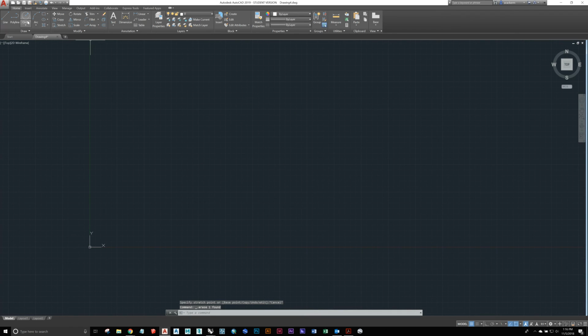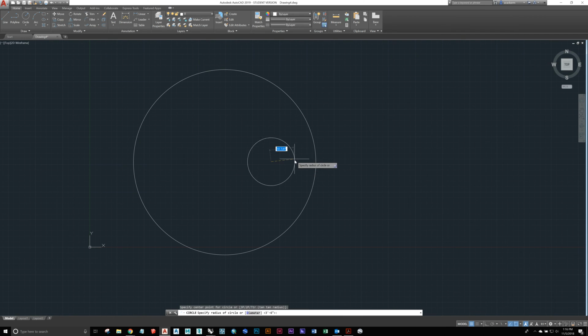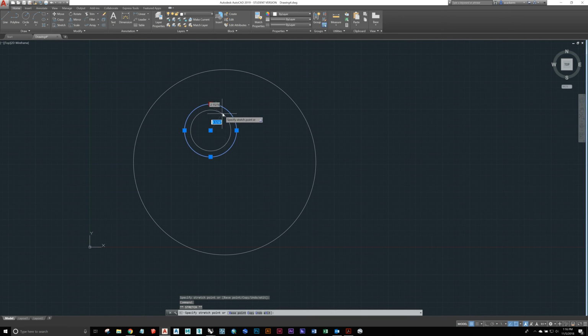You can also draw a circle, starting with the center and specifying the radius. You can do this in feet or inches or a combination. So let's say 3 feet 6 inches. Enter. Draw another circle. 1 foot. Enter. These circles operate independently of each other. They can be moved to the center point. You can also further adjust their radius by clicking one of those handles.